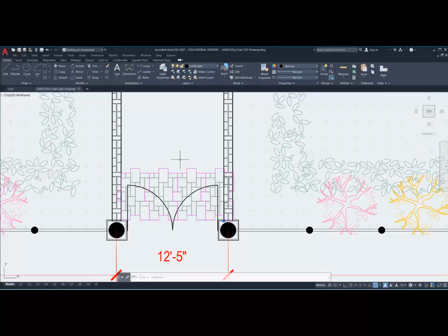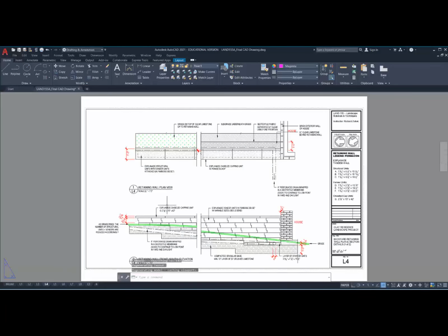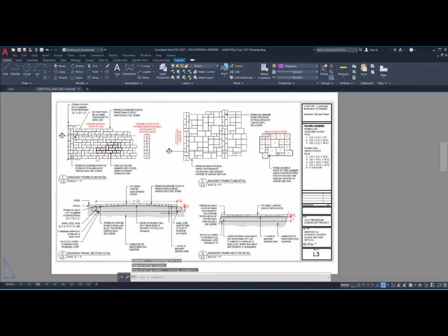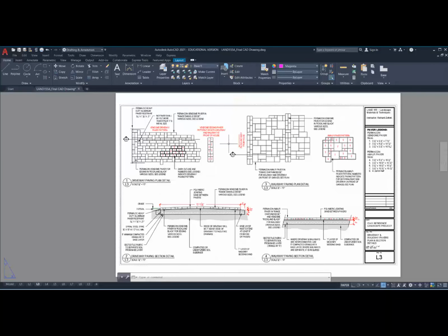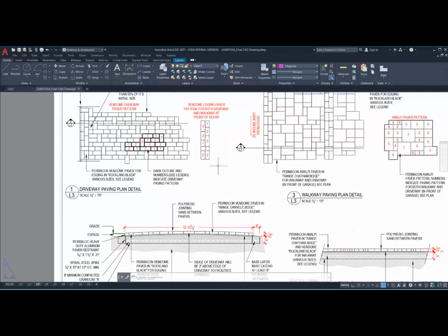So these are all design considerations of the earliest of stages, so that when I actually go to draw my details, my tile details, I'm going to go to L3. There is the pattern. Notice how you want to make it fit along the edge and what the edge pattern is. This is all critical to the excellence of the installation. We don't want a haphazard, as it fits into space, cut the tile, but also think from the perspective of cutting the tiles, how efficient it is.